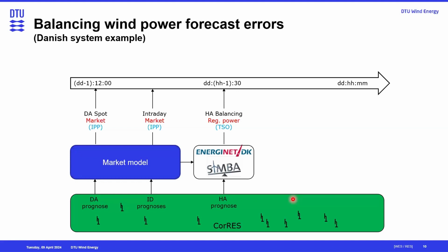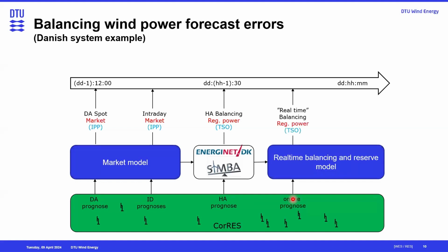I can call them and they can provide it, and that way I can get many more reserves, which are offline now, come online, and they are cheaper. They can be coming from gas, from hydro or some small CHPs, DCHPs, and they are cheaper. If I don't do that, then I go into the real-time balancing, because even the hour ahead forecast has some error, which has to be taken care of by real-time balancing. And real-time balancing has to be taken care of by the automatic reserves.